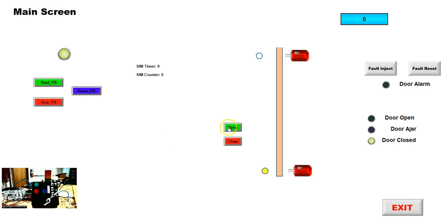Now, as soon as I hit open, it's going to start counting up. I should see that counter, like the timer just runs, it's counting 10 times a second, so it's counting 0 to 100, and it's just repeating it over and over. Now, it again is going to be really fast, but what I really want to see is this 0 to 120. And so as soon as it starts going up, this light goes out, that motor goes on, which says the motor up is going on. So let's see. So yeah. That went out, that turned on, and the door closed went out.